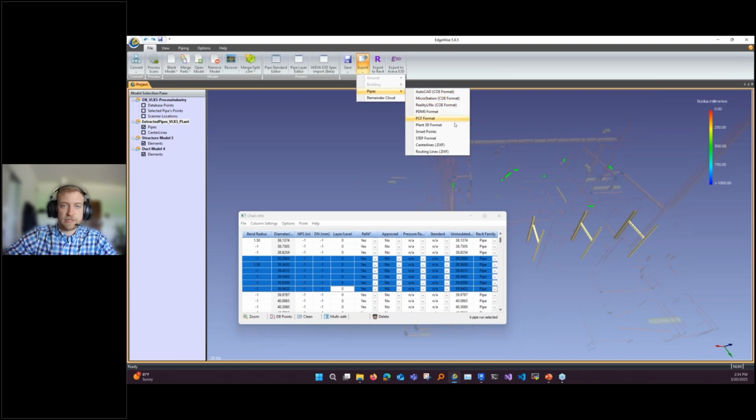And basically going through, we have smart points. So this is a point cloud export. This one actually is super cool. This will export a point cloud that's only points near the geometry you have selected. So if you think about breaking this up, you can export all your piping systems into one export for going to Revit for all your different system types.